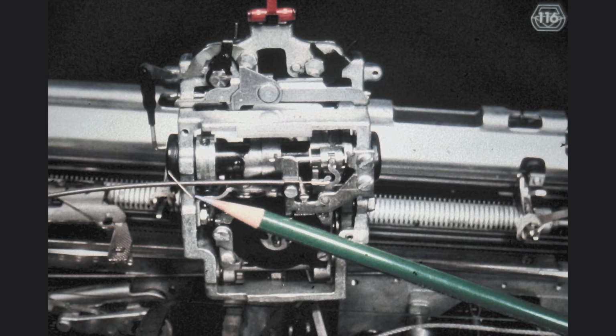It is extremely important to be aware of the function of this guide spring when working with the dual impression machines. This guide spring prevents the velocity control cable from becoming entangled with the carrier return pulleys when the carrier is at the extreme left margin. It simply keeps the cable above the cord pulleys.